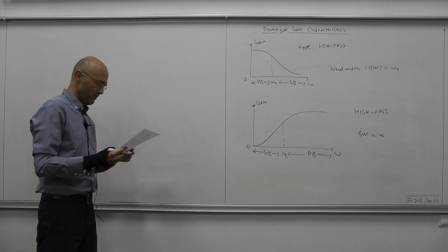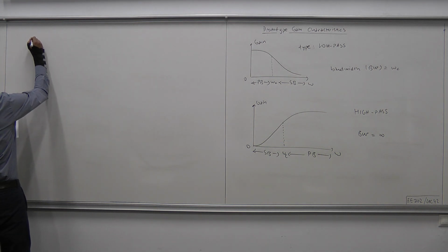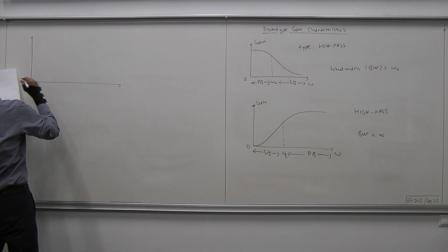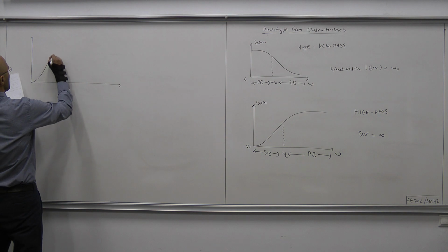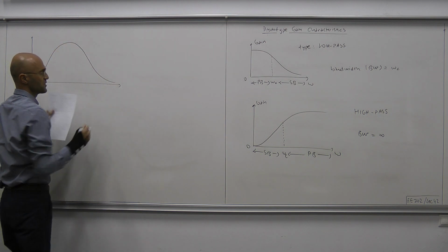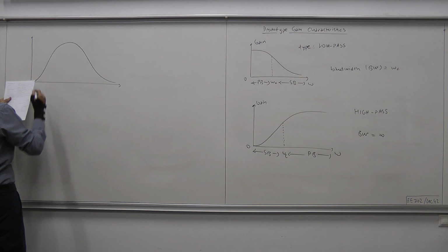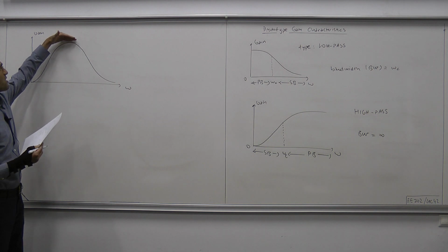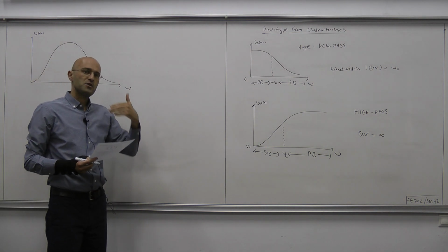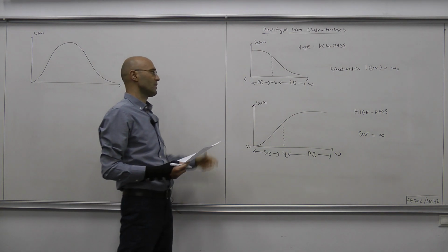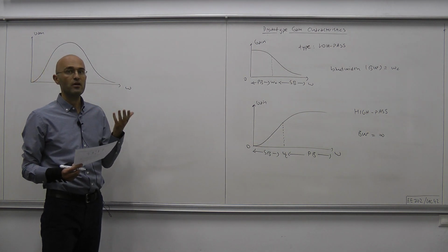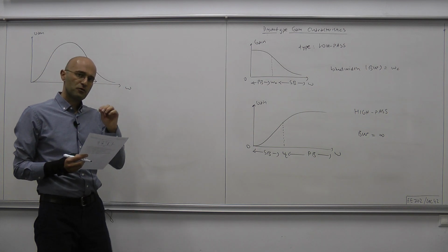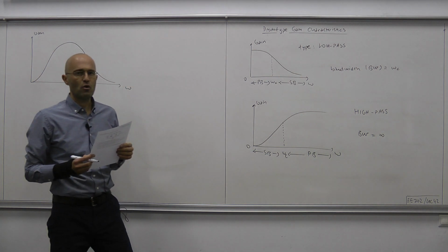Okay, now there are slightly more sophisticated gain characteristics. Or more selective, let's say. Here's another type that we will study. Okay, it has this bump shape, gain omega. So the maximum is somewhere here, and then to figure out the cutoff frequency, what we do is we multiply or we scale that maximum value with 1 over square root of 2, and we figure out the corresponding frequencies, and those frequencies make our so-called cutoff frequencies.